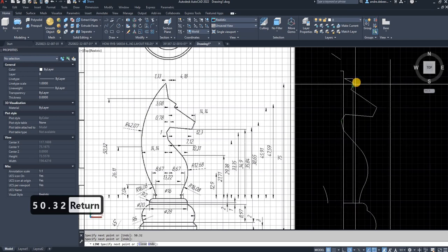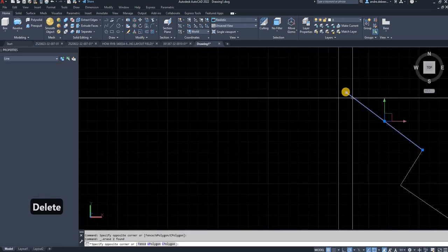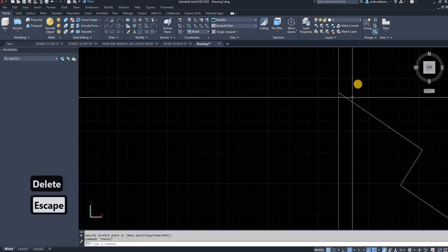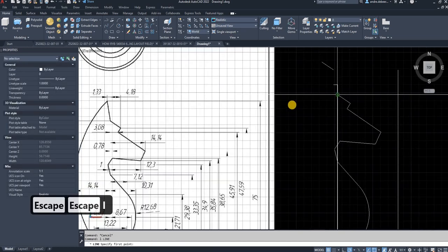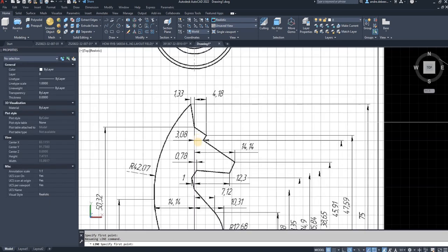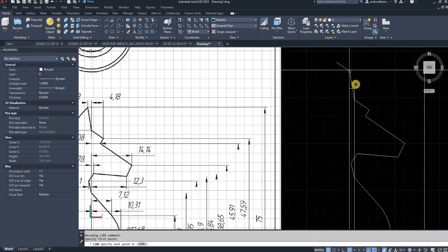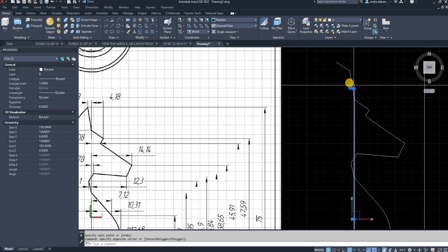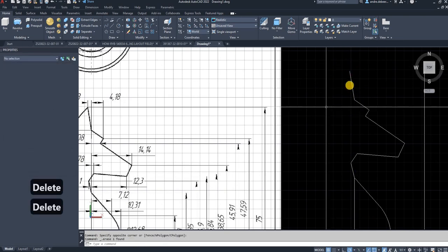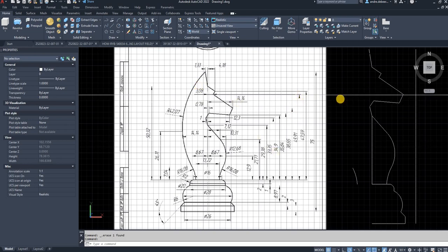It's going to be on the center line as shown. I'm going to remove those two lines. And from there, you can use that point that I've previously drawn. Delete that line, delete that line, and the last thing that is left to do is to draw this arch of a radius of 42.07. So you have that point, you have that point.